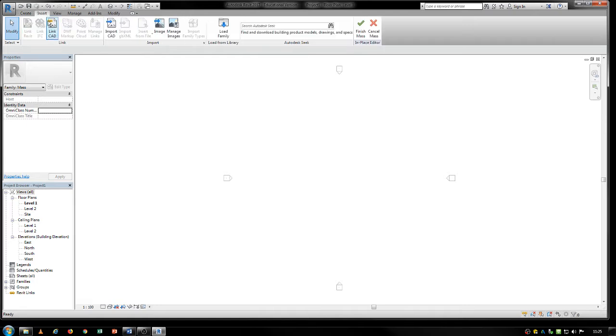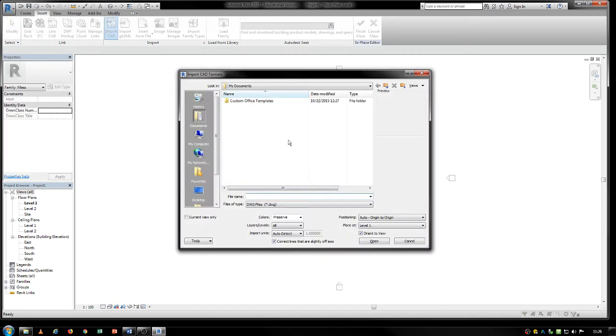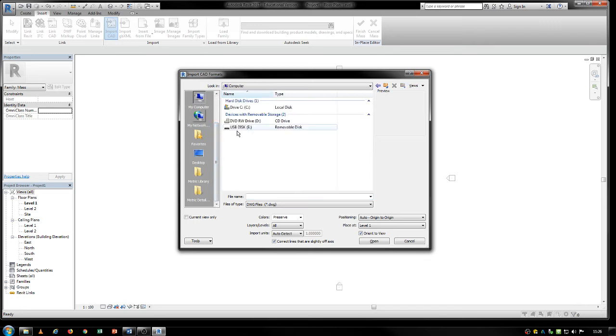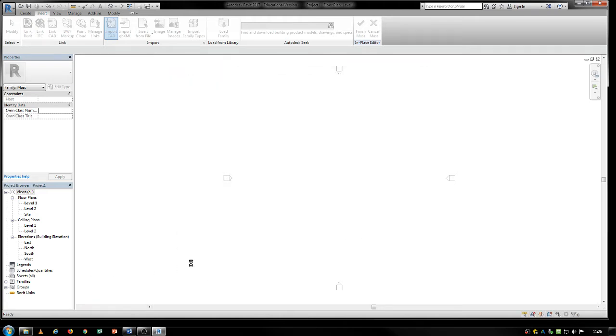Okay, so if I go to insert and bring in a file, you know the differences between importing CAD and linking a CAD file, right? Yes, okay, good. So I would import a file here from the ones that I have. I want it to be an SAT because I'm working with NURBS systems. Then it's automatically detecting my scale. I just want to say, okay, it's in meters or millimeters, whatever my original is, if I don't want to auto detect, and then it will bring in my mass.